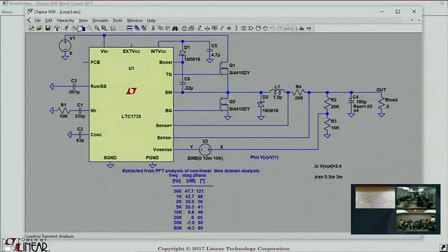That's exactly what just happened. See, I said, what's the phase shift from the inductor? You all recognized the danger, silence, right? Just exactly the same thing. Then one person said something, got everyone a little looser, more comfortable. Eventually they said, oh, it's 90 degrees. And they all said, yep, it's 90 degrees. And it's exactly like the penguin with one difference, and that is this time there is an orca, and he eats the penguin, because the answer is not 90 degrees. The answer is 0.